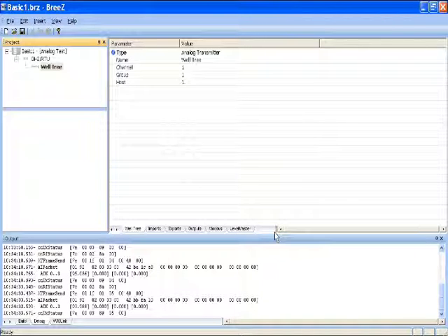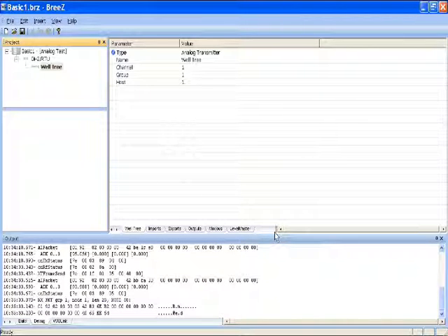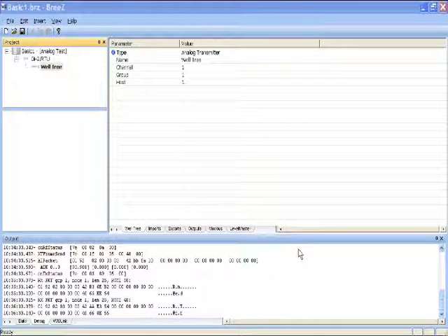Now move your configuration cable back over to the DH2. Now, with the cable in place between the PC and the DH2 and the debug window open, we can clearly see the RX packet Group 1 Node 1 with a length of 26, RSSI value of 50 has been transmitted to the DH2. We should see this happen every 1 minute because that is the interval that we have set. Now that we have confirmed data is coming into the DH2 at a good receive signal strength, we are ready to set up our Modbus master to request said Modbus registers.